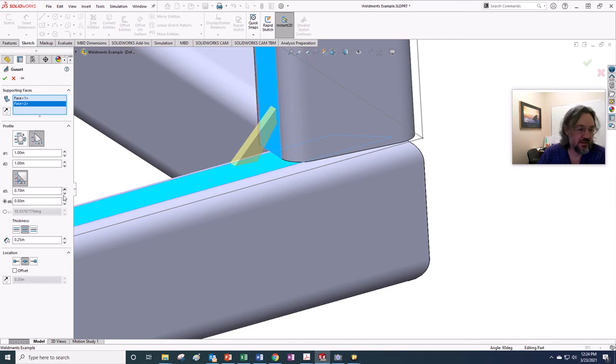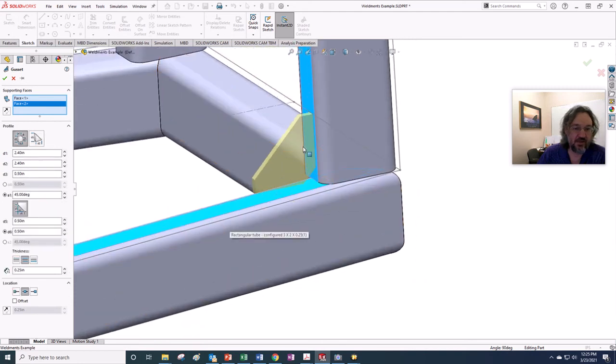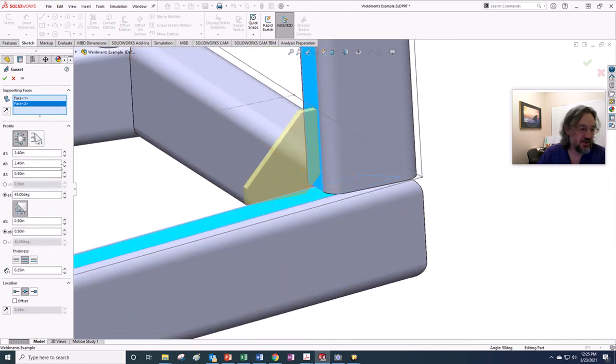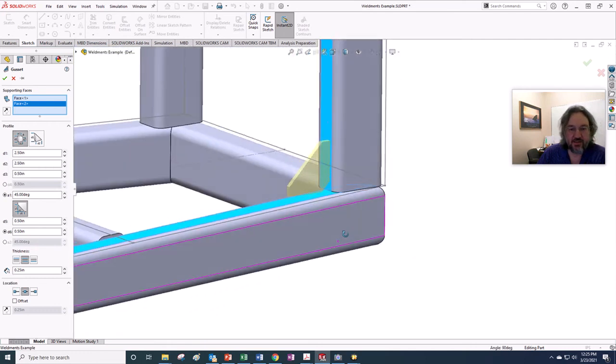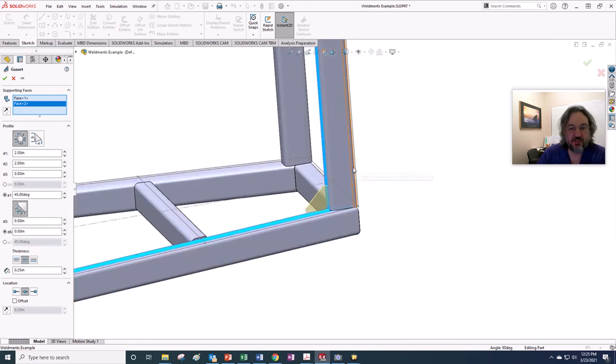But you can kind of see. Let's make this thing substantial, right? Actually, we could take a look at it, and it's nice to put a little, we call these toes, a 1/2-inch toe on the thing, so maybe something like that right there as a gusset. You want to take a step back and take a look. That's kind of small. I think 5 inches would be probably about what I would say.